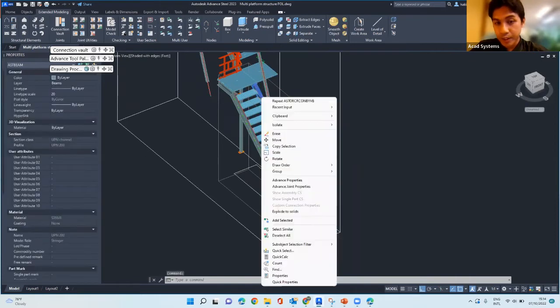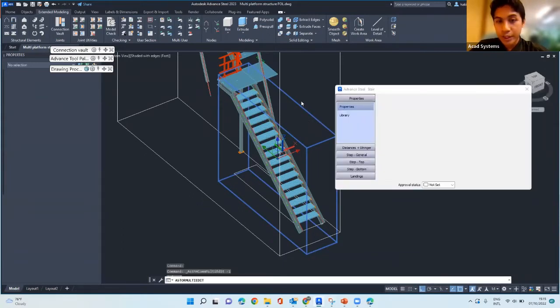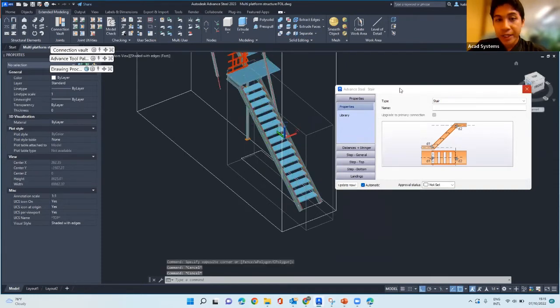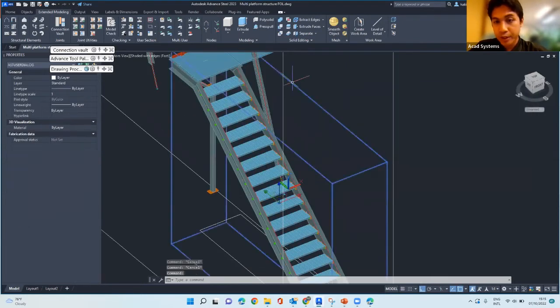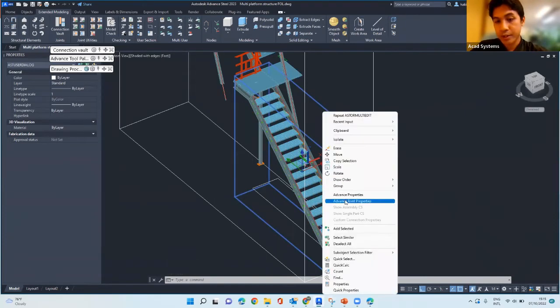click here and then right click on your stairs, and then there will be this advanced join properties. It will load a little bit, and then it will bring you back to these properties, so you can revisit this window and make further edits. Once you apply that, you also realize that there will be this box around our stairs. This is the indication of that advanced join properties. You can also right click from this box to get to that window.